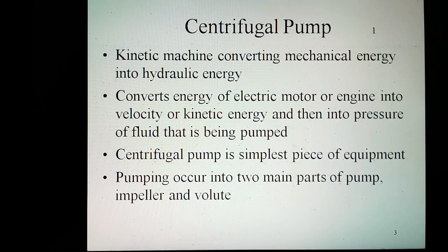The centrifugal pump is a kinetic machine converting mechanical energy into hydraulic energy through centrifugal activity. Its purpose is to convert energy of an electric motor or engine into velocity or kinetic energy and then into pressure of a fluid that is being pumped. The centrifugal pump is one of the simplest pieces of equipment. The energy changes occur in two main parts of the pump, the impeller and the volute.